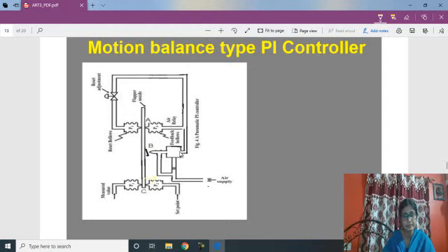This is simply the pneumatic nozzle system with the air supply; I am not repeating the nozzle action. If the flapper moves towards the nozzle, the nozzle feedback pressure will rise, and that pressure will go to the feedback bellows element after a small time delay.